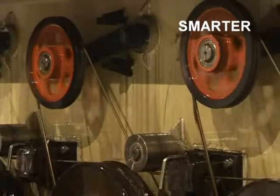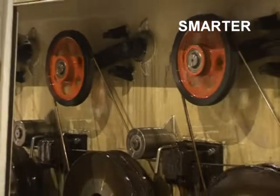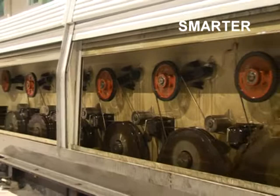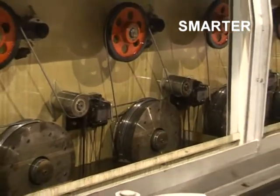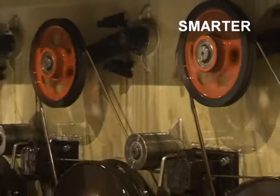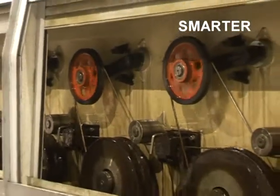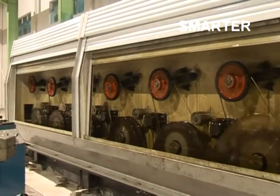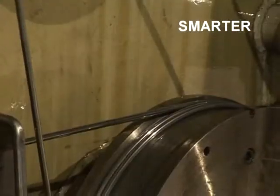Between each capstan, there is a speed feedback system to complete non-slip drawing, as well as extend the lifetime of the ring and the die. The diameter of the drawing pulley is 450 mm, and the surface is coated with tungsten carbide and arranged in one row. The rigid shaft is a short cantilever to apply for high-speed rotating.